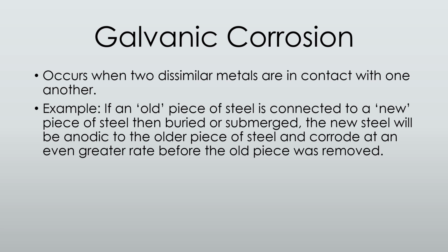So now that you've brought those two in contact with one another, you've created essentially a battery. You've created a greater voltage difference than was present before. So you'll actually have a failure again, probably in a fairly short amount of time.